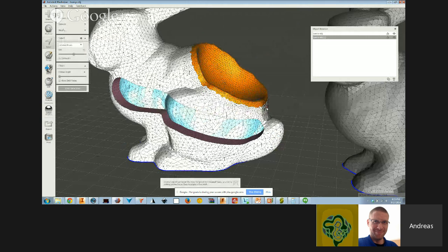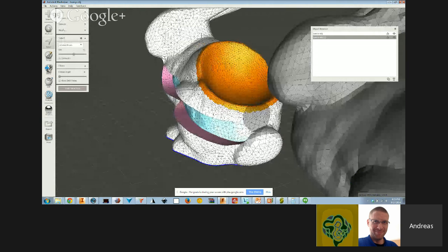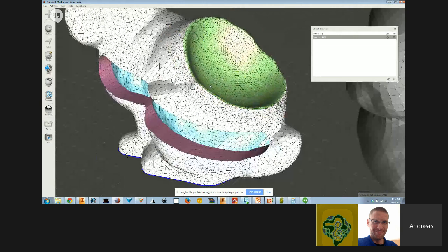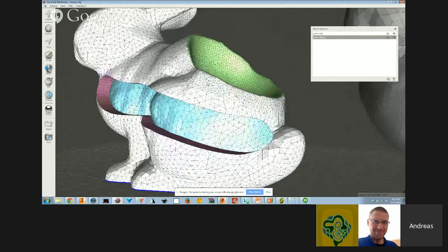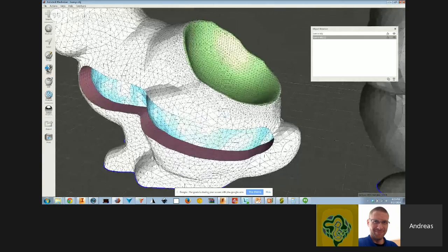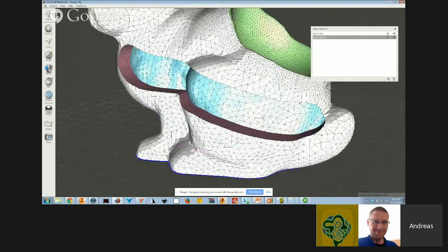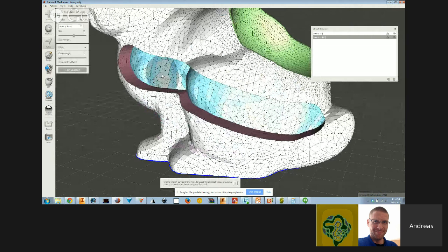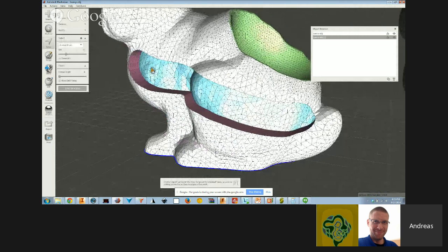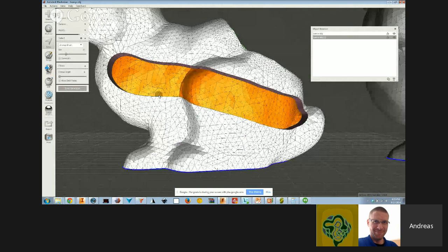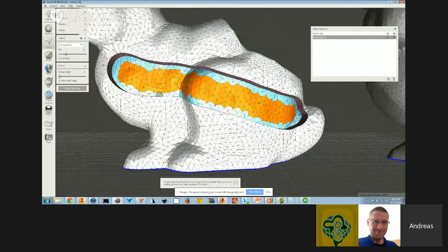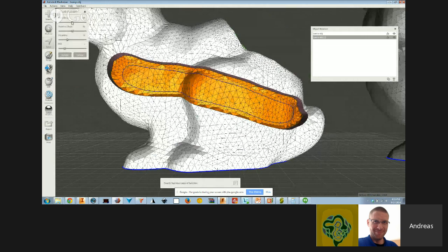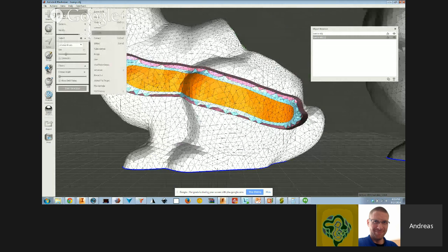And now I still have the face selected, and I can escape, and now I just have a much smoother thing there. And you can go deeper and deeper into this, but that's basically a face group. So I can come in and again go into select, which is, if you just tap S, you enter select mode. Decrease the size here, and I can just quickly select this thing, and let's just say I smooth the boundary again. Hotkey is B, and go and extrude it or do something like that.